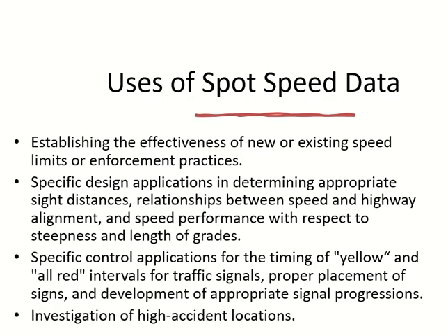High accident locations. If you feel at a particular location the accidents are very high, a spot speed study is 99% of the times part of the investigation. Why are the accidents higher?